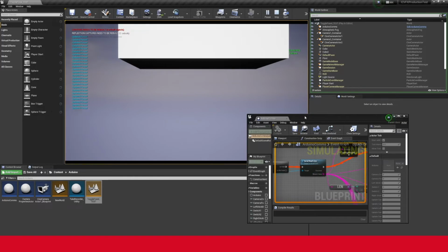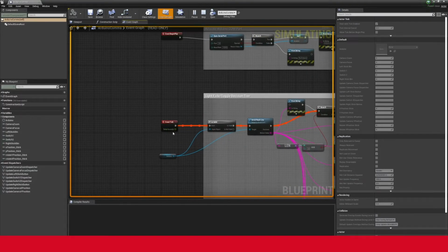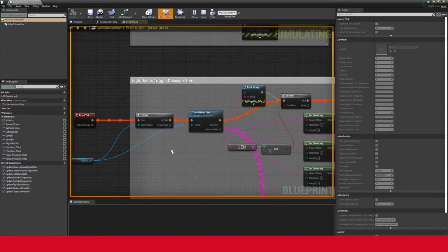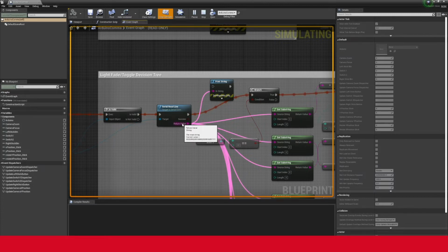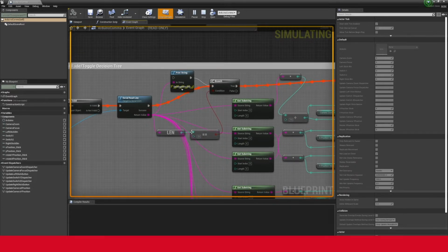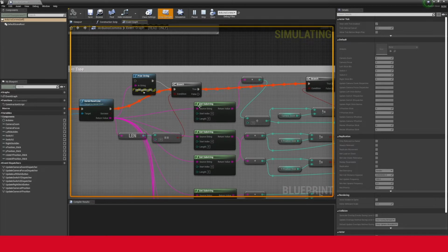So let's explain exactly what's going on inside of the blueprint. What's happening is on tick, we check to see if the Arduino is connected, and then from that we'll read the line, and you can see it's reading a line here. Now we want to check that the length of the string is around 28, right? So that's all the sensors combined, that's how many characters we're expecting. So if that length is correct, well then it's going to execute this. If that has any issues, maybe the COM port truncates it, and then it's going to reject it and do nothing, right? So previously, before me modifying the actual way that the Arduino Sketch worked, it would always trigger false when it was essentially just truncating it by accident, right?